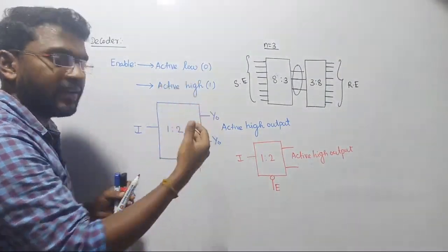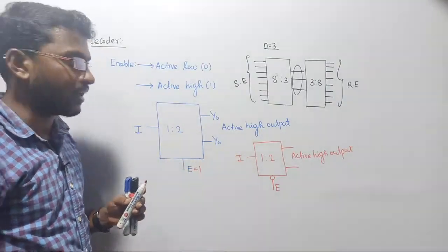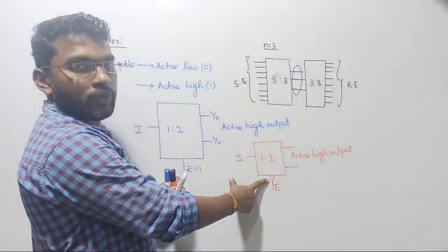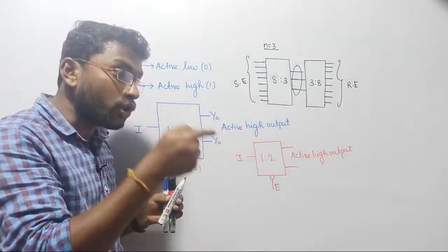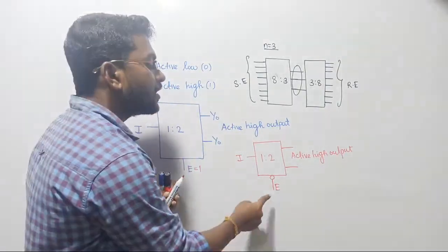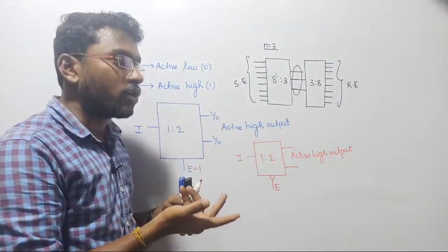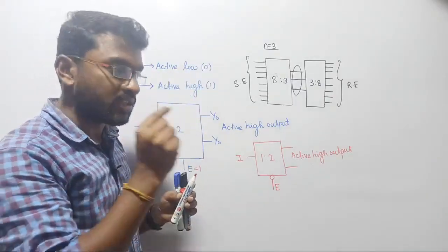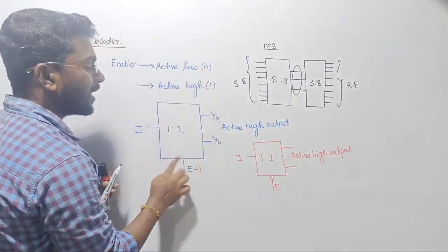We are using some gates at the back, and those gates will be triggered with the help of this electric signal. Now coming back, if you want to transmit, here they are using one inverter. In order to pass the electric signal inside the circuit, from outside we should consider 0, because only then that 0 is going to be inverted by the digital gate. Then 0 will automatically become 1, and passing 1 means an electrical signal is passed through the circuit, so your circuit is enabled. That is what we call active low and active high enable pins.